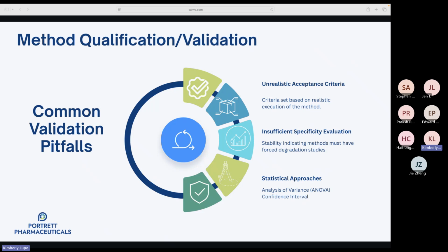So everything is still within its validated parameter space, and nothing has really gone wrong, but now the precision is running at 1.2% RSD, and recovery is 98.5 to 101.5. The root cause is that you set your system criteria on what you observed under ideal conditions rather than what you need for the method to be fit for purpose. Your acceptance criteria should be based on your ATP requirements, not your validation performance.